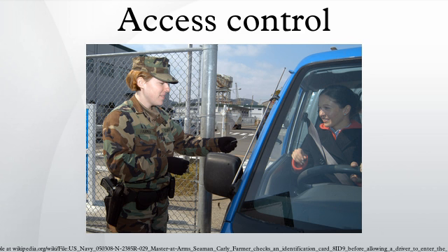door is opened. Exiting a door without having to electrically unlock the door is called mechanical free egress. This is an important safety feature. In cases where the lock must be electrically unlocked on exit, the request to exit device also unlocks the door.